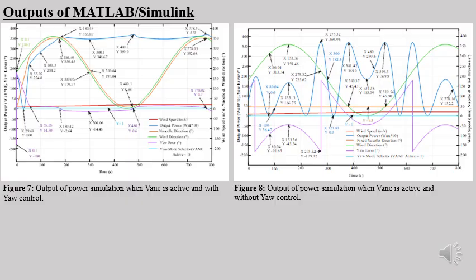While the yaw error stays within this band, the controller avoids unnecessary rotation, which reduces motor wear but still maintains stable power. The best alignment occurs around 480 and 778 seconds, where the yaw error is almost zero and power peaks at about 3.67 kilowatts.